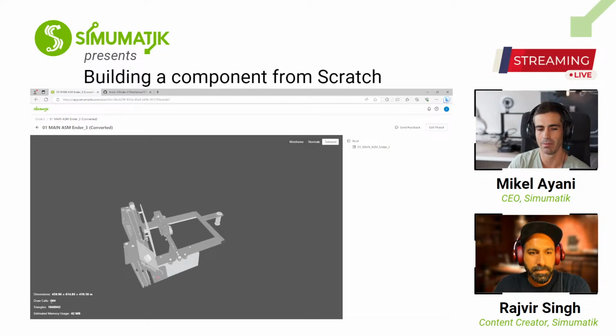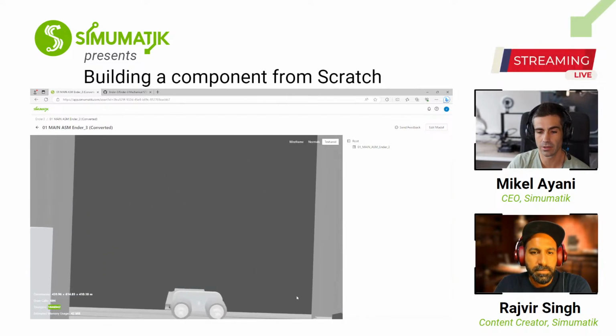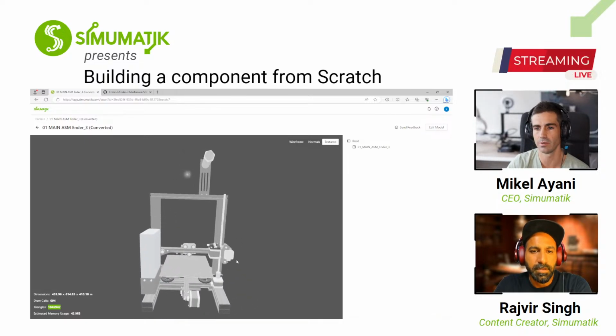You see here the numbers. This is almost 700 draw calls. This is huge, and this is how it looks. It looks nice, but we have 2 issues here: almost 700 draw calls, and then over a million, almost 2 million triangles. It's a nice looking, very detailed model, but it's not what we want if we are going to build a component in Simumatik.